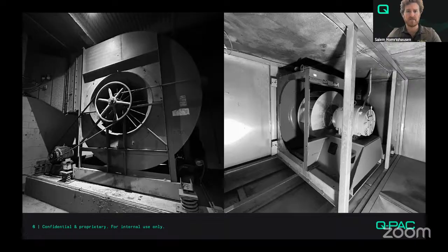Shortly, once this product started to be phased out a bit, or you start to see less of them, these single plenum fans over here on the right were kind of what replaced them. So the idea was with these designs, you're going to have one single fan that's going to supply air for a space, and the idea being that you're going to get the most mechanical efficiency out of a single large impeller that's going to provide all the airflow for the space. So that was kind of the primary design philosophy around these products.